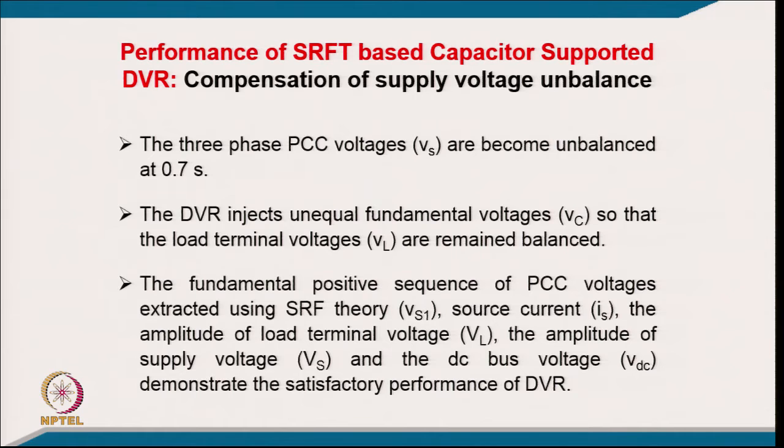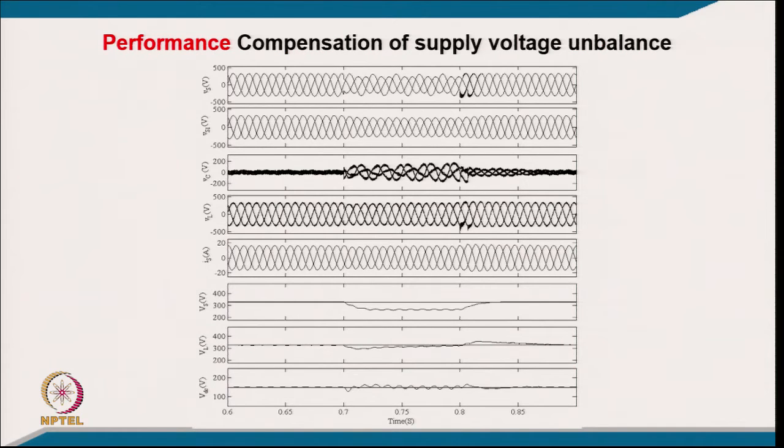Coming to the performance of this synchronous reference frame theory based capacitor supported DVR for compensation of supply voltage unbalance, the 3 phase PCC voltages become unbalanced at 0.7 second, and the DVR injects unequal fundamental voltages so that the load terminal voltages remain balanced. The fundamental positive sequence of the PCC voltage is extracted using SRF theory, and the source current, the voltage amplitude of the PCC voltage and the DC link voltage demonstrate the satisfactory performance of the DVR.